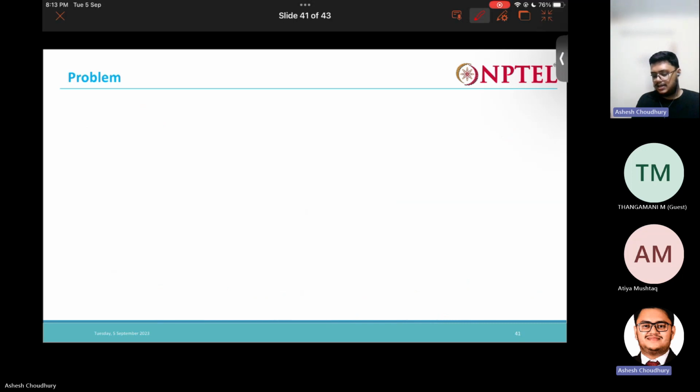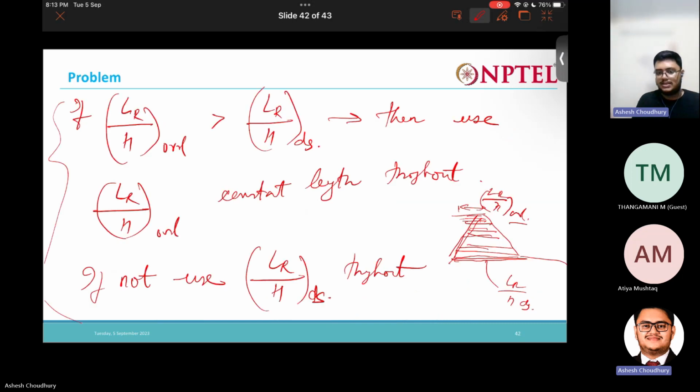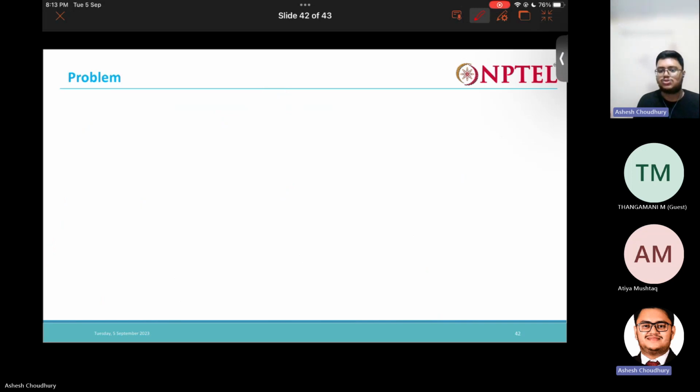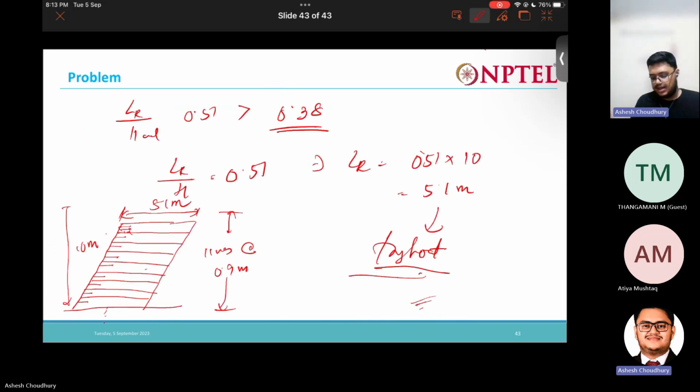After that, we checked the overall length and the direct sliding length, and based on these we chose the length of the reinforcement. Finally, we gave the panel diagram of the reinforcement.